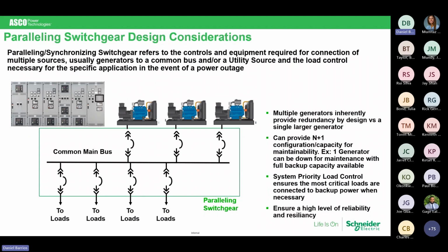When we have an outage, start all 3 generators. By the laws of physics, one will hit first, locking out the other 2 momentarily. However, as soon as that first generator hits, it is going to immediately have load transferred onto it because all of your 10-second life safety loads, Article 700, need to be on in 10 seconds.